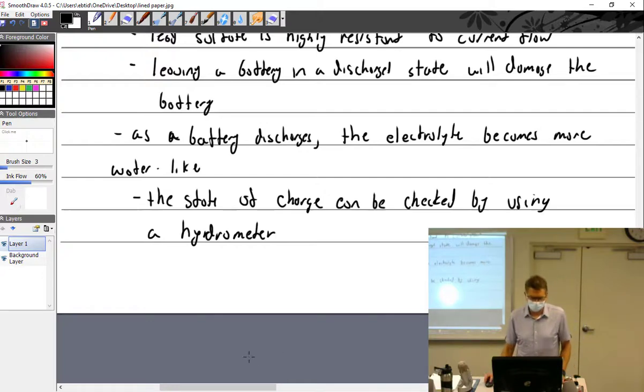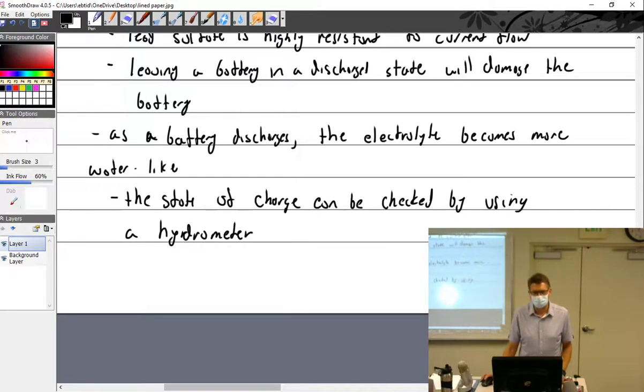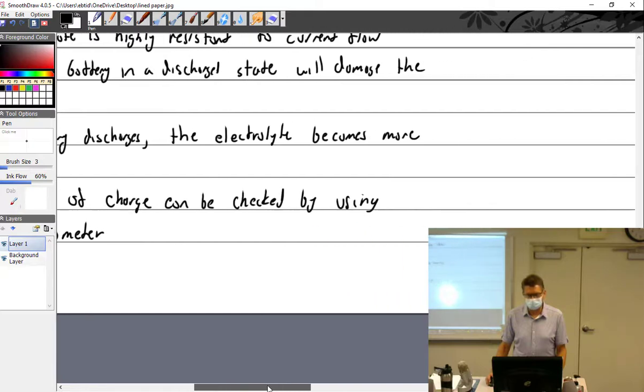And I was sharing with you yesterday about the charger that we had in our shop and paint room. This is a long time ago. One mechanic, when the battery went bad, did the equivalent of that, but what he would do is just clamp it on and crank the amps up. It's literally bubbling. You can see a mist over the battery because it's just gassing. You can smell the hydrogen just pouring out of that room. What he was doing was blasting the sulfate off of the plates, giving it such a high amperage that it would actually kind of do that. And that would actually kind of work for a little bit after that. You also warp the plates and cause shorts and stuff like that.